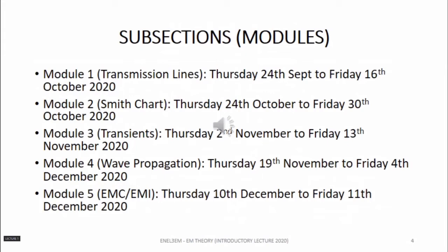We'll then determine the reflection coefficient along the line, and we'll also determine the standing wave ratio on the line. And as we determine the standing wave ratio pattern, we'll now ask ourselves what happens when along the line you have voltage maxima and minima. At those points, what is the corresponding input impedance? And then we will also determine the power delivered to the load, depending on whether the line is terminated in a matched load or on an unmatched load.